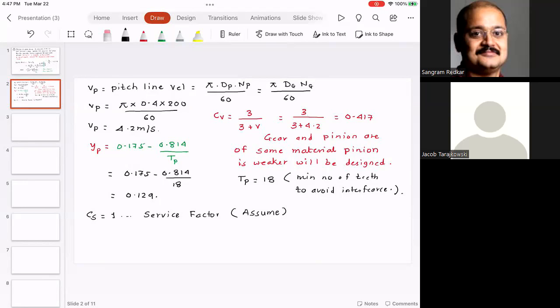So if a machine is designed for commercial usage, then the service factor would be high, because we anticipate that it would be loaded more and used in a rough fashion. That's why the service factor is, sort of, how heavily the machine is used, or the operating conditions in which the machine is used.